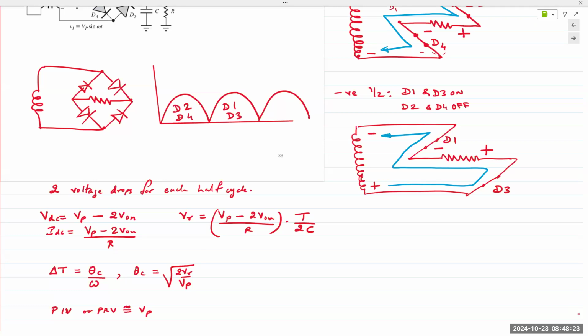So you can't use it anywhere else outside of North America. But all the mobile devices, mobile chargers, doesn't matter what the input is, going all the way from 100 to 240 volts AC, the diodes can handle that high value of an AC signal. You simply rectify it directly into DC, then it's converted to a lower voltage after rectification. And so all chargers that we use nowadays can be used anywhere in the world. You don't need an electrical conversion. You only need a physical conversion.